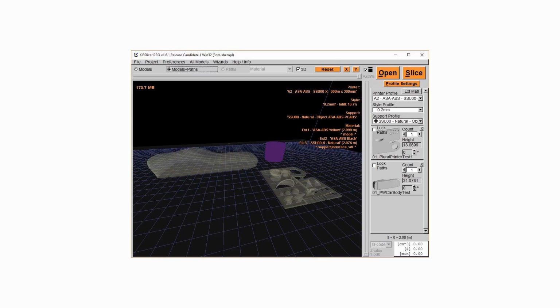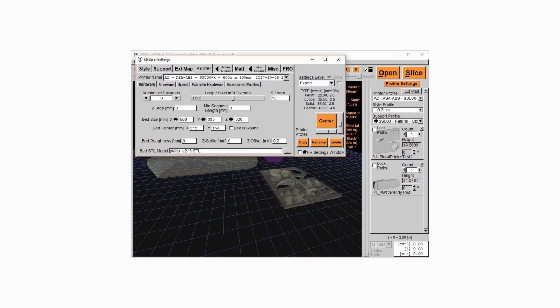However, it would also make it slightly easier to break the car in half. Conversely, flat brackets should be printed laying down for optimal part strength. More complex parts must be oriented for the best compromise between strength and surface quality. Now open the Profile Settings window, and with the settings level at Advanced, all settings are unlocked.